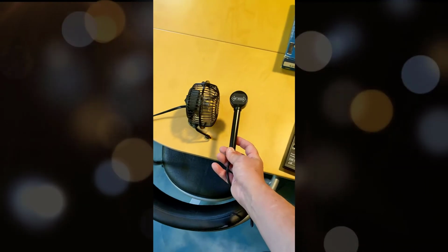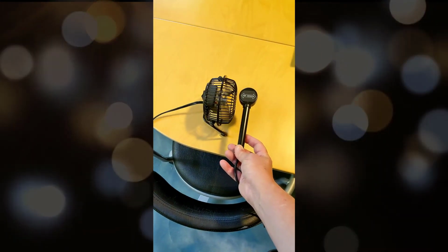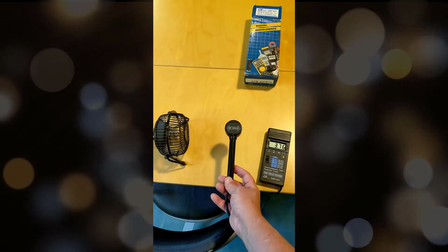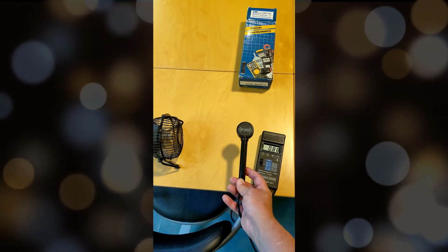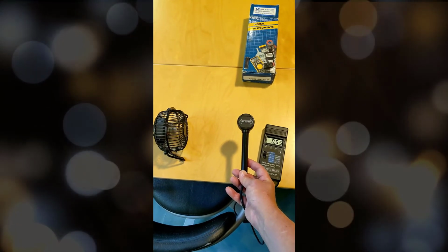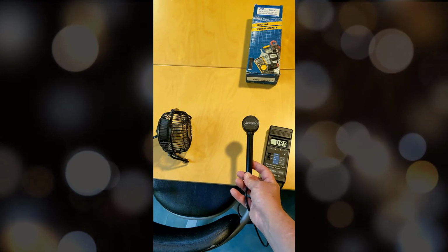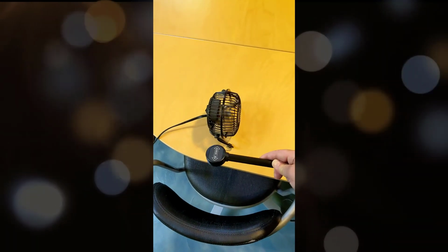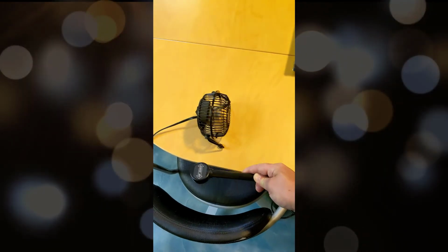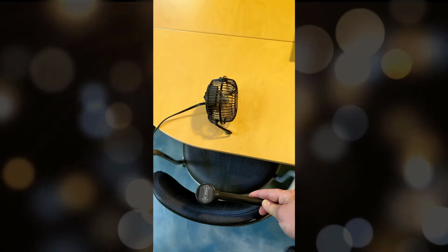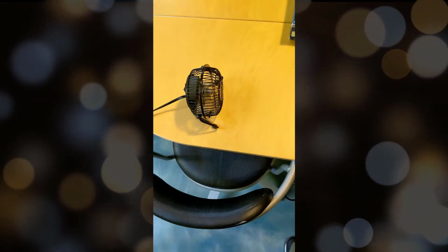You can see it drops off fairly quickly between 10 or more and 1 in the span of about a foot. So the field strength drops off with the square of the distance, and for a motor like this, the field is greatest to the side. So now that's one significant source that you can expect to find.